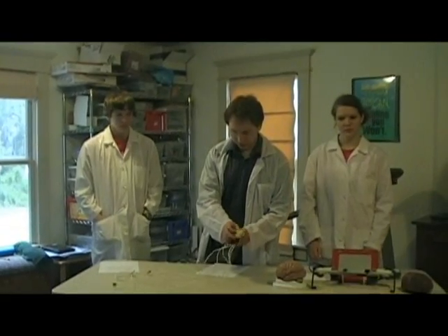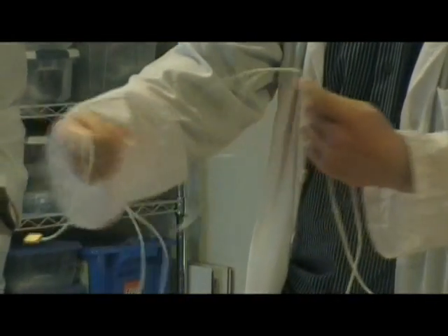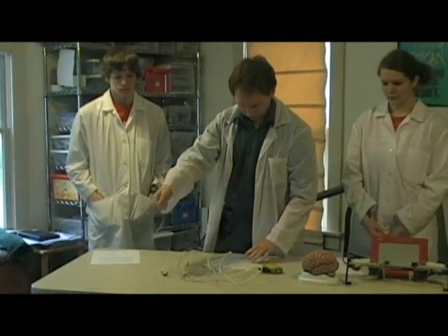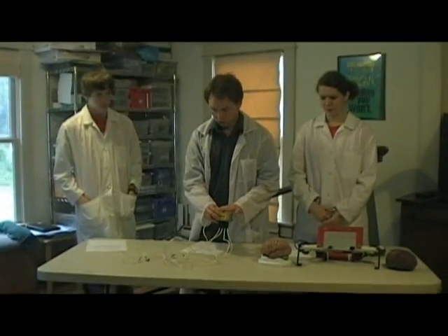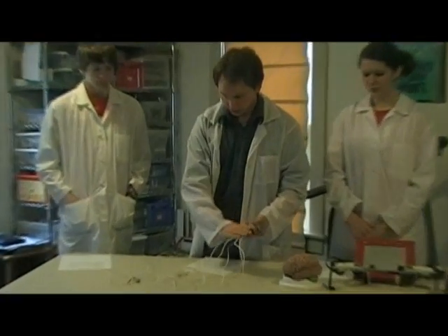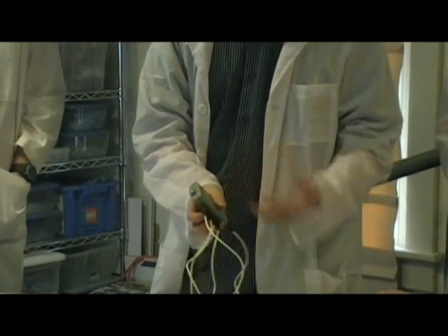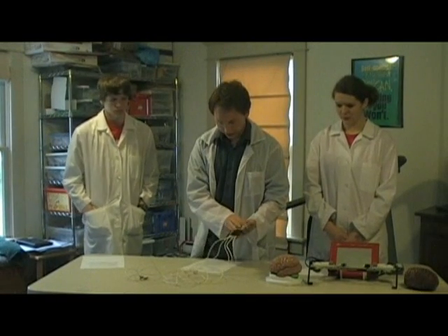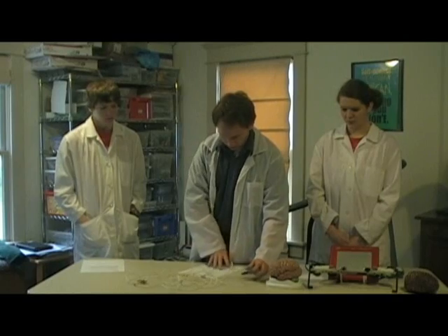This box is the EEG. It has 4 electrodes, which are separated into 2 channels, and 1 driven right leg, which is essentially a ground. Within is an analog board, which takes the signals from the electrodes and filters and amplifies them to make them more usable, and a digital board which digitizes the information for sending to a computer.